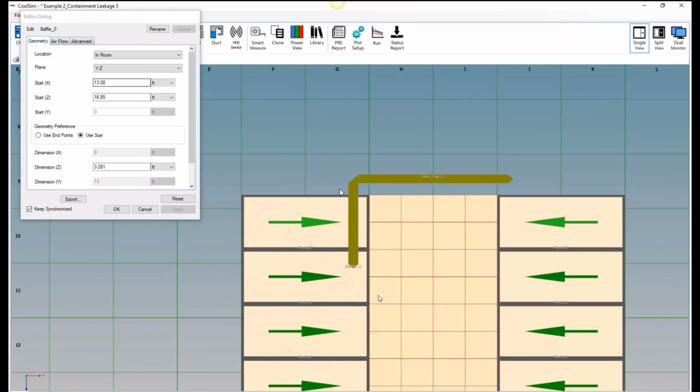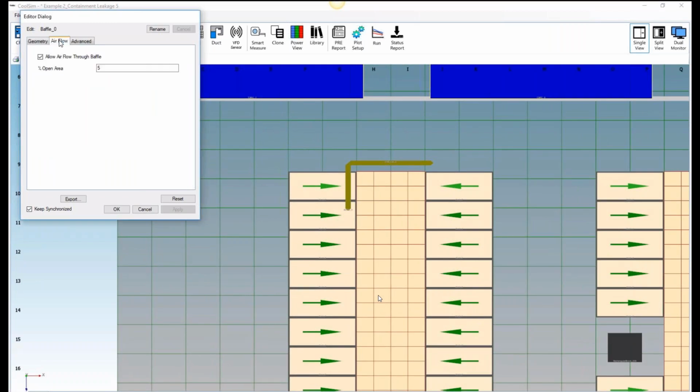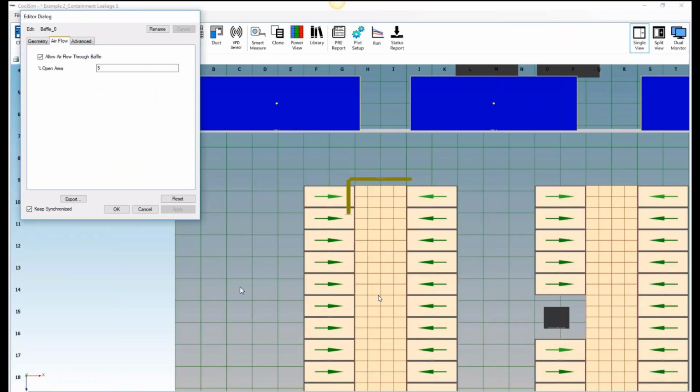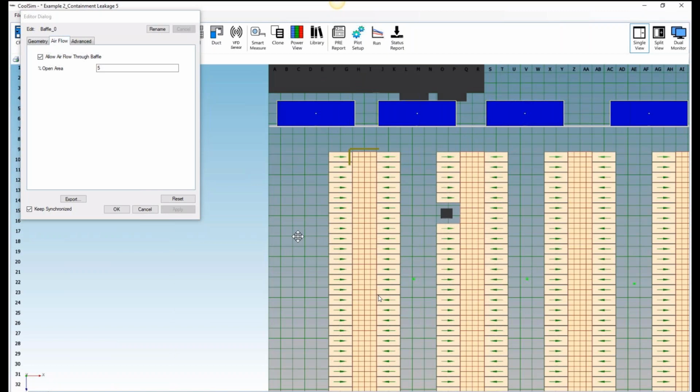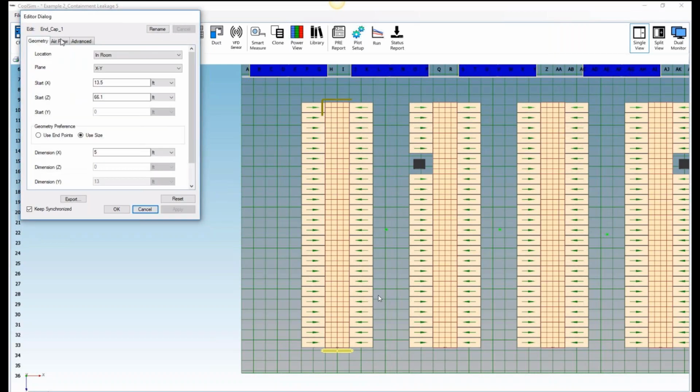They should look like a 45-degree angle, just like I've shown there. If there's a small gap in there, the mesher assumes that you're interested in that, and it will mesh the hell out of it and drive up the mesh count and drive up the solve time. So you want to make sure that it's lined up correctly.